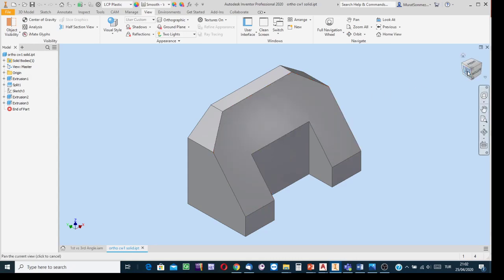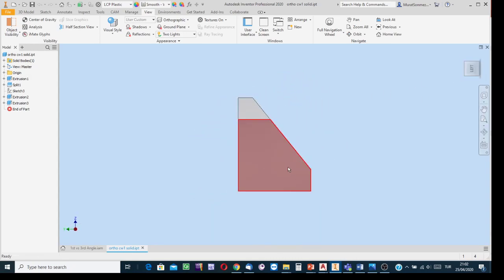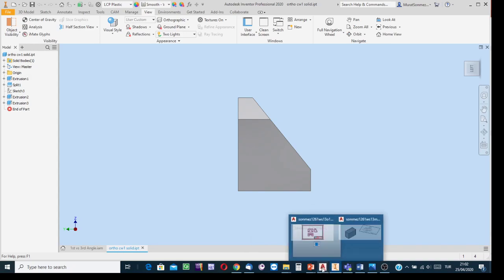Over the surface, the necessary sketch uses the edge of the surface that is to be created. What I mean is, on the left side surface, draw a line. It corresponds to the edge of the surface which I selected to create its model. Okay. And then over the surface, draw the H view of the surface. And then to have a closed region, a closed profile, draw the other boundaries. And thereafter, apply the extrusion process. Yes, I'm going to do such a thing.